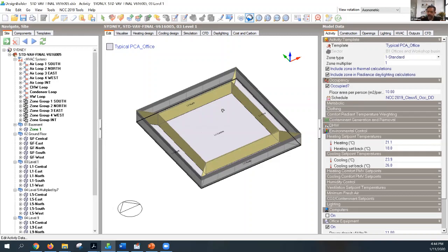They're not really walls, but they're mathematical constructs that air conditioning engineers use so that they can design air conditioning systems for perimeter zones and center zones. If you are not able to calculate the loads that each of these perimeters pose to the air conditioning system, then it's very difficult to size a system correctly.